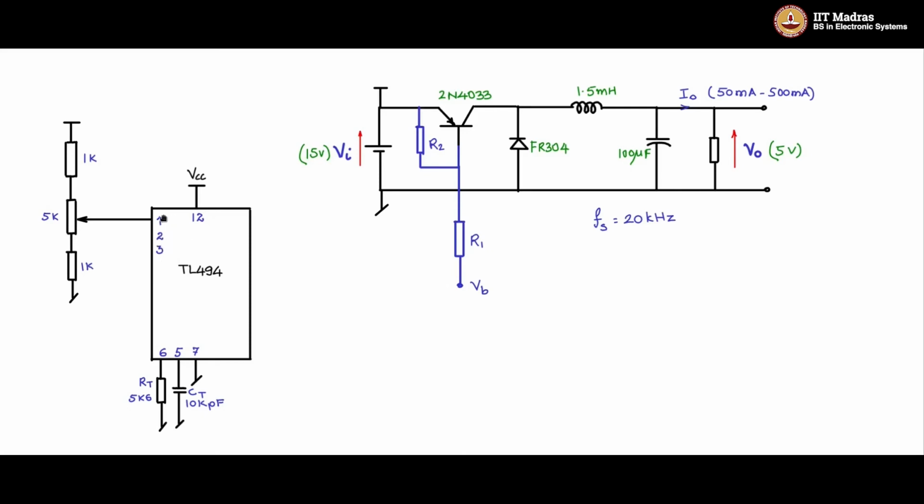Pin 2 and 3, now 1, 2, 3 is an error amplifier. Pin 1 is the positive input and 2 is the minus input and 3 is the output. So you can short 2 and 3 to make it in the voltage follower mode. There is also another amplifier which we can disable. So let us say pin 4 is the DTC, the dead time control pin.